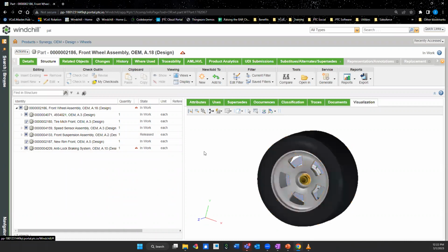One of the benefits of using Windchill is how we have set this structure up. It's not just your typical bill of materials. If you've worked in a PDM or PLM system, or you're at least familiar with them, a lot of times the way this works is you have your CAD assembly that you are managing in a PDM system, and your BOM is essentially a copy of the CAD structure. You have your assembly file at the top, you have the sub-assemblies, each one has a raw file in here, and that's what's building out your BOM.